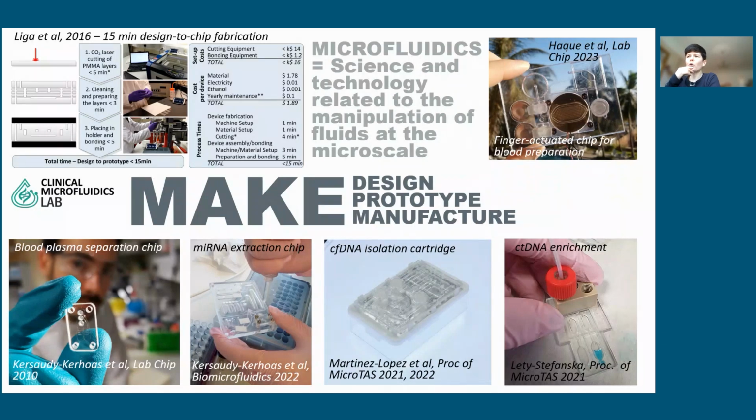And in doing that, I also moved away from the clean room and photolithography associated with the electronics industry and developed an ultra-fast prototyping method using a layer-by-layer cutting of acrylic sheets and a solvent-assisted thermal bonding method. And there were several reasons for this. One, unlike photolithography, which could take days, if not weeks, to get the device prepared, the ultra-fast approach enabled a full or even several design-to-test cycles in a matter of a single day, so massively accelerating our research.